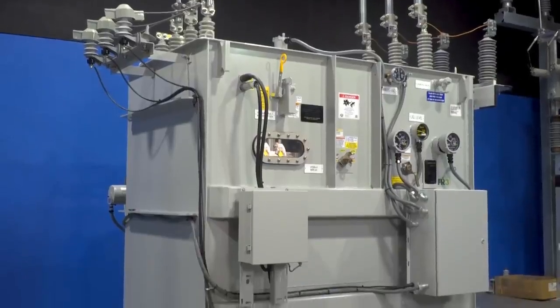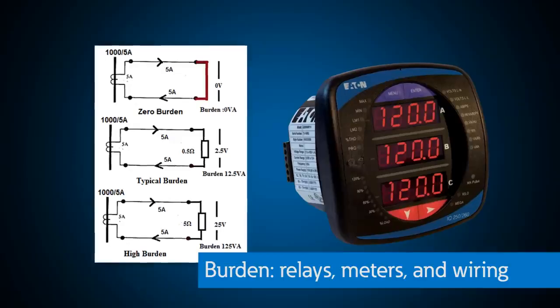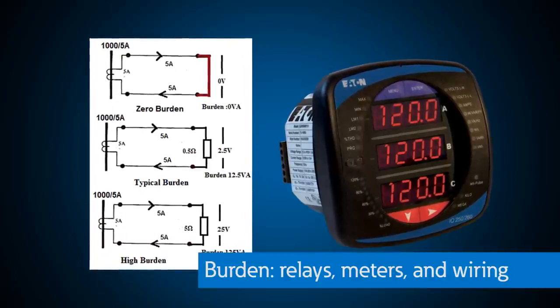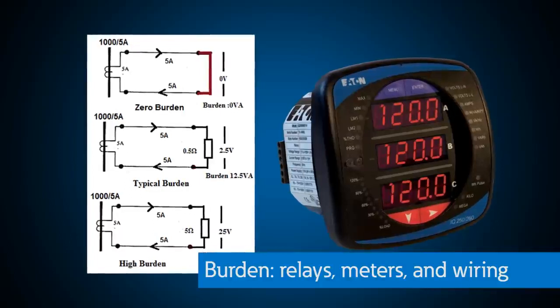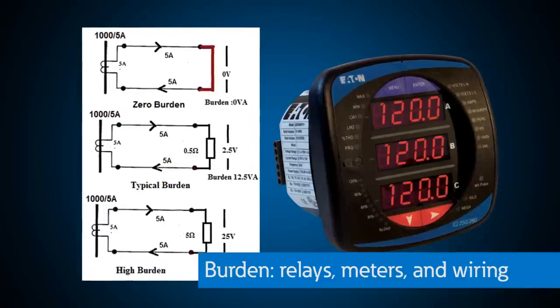Like all transformers, CTs have volt-ampere or capacity ratings. CTs have limits to the number of devices and length of wire that can be connected to its secondary side, which is called the burden. Items that contribute to burden are relays, meters, and wiring. The best way to reduce burden is to keep the conductors between the CT and the metering devices as short as possible, or increase the wire size to reduce resistance. The burden for today's modern electronic relaying and metering is very low compared to older equipment, but care must be taken to ensure CTs are not overloaded or inaccurate current measurements or protection will result.